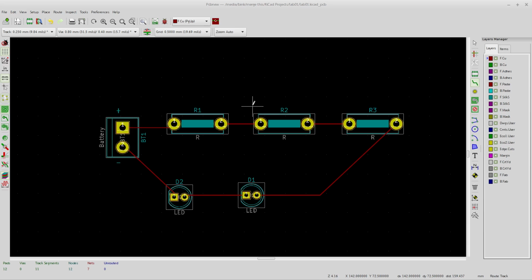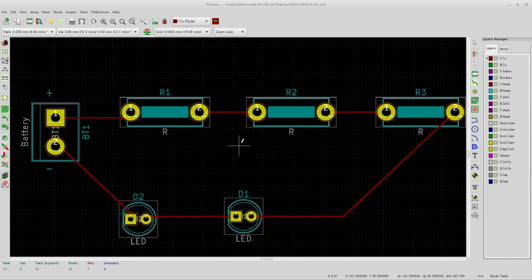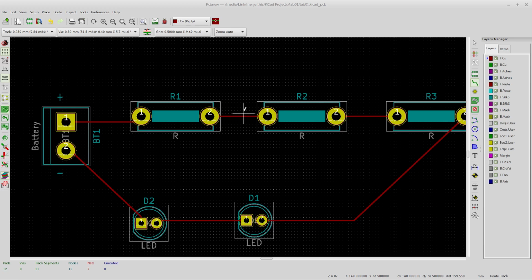Now, the thing I was going to say about making a bridge, sometimes you'll see this around. You might be looking at a board and you'll find a little surface mount resistor somewhere, or maybe in the older days, just even a regular resistor, or a wire that's 0 ohms. And you're like, why the hell did they put a 0 ohm resistor in here? And I guess you could put it in as almost like a fuse, like some kind of extra protection that maybe it's got low wattage and it'll pop or something. There are other better ways to do that.